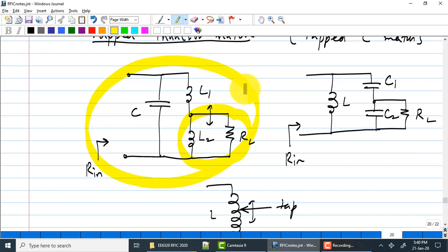At the input of the receiver, you are more interested in noise figure. You want to be as low noise as possible. At that stage, it is indeed possible to do active matching, which can sometimes be better than passive matching. And we will indeed look at both types of matching, both active matching networks as well as passive matching networks.